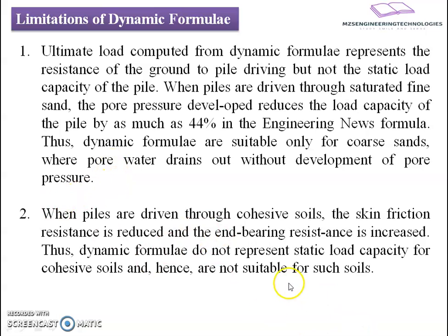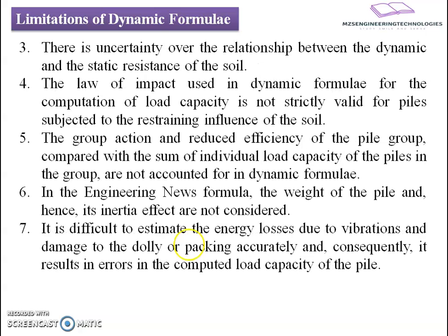When piles are driven through cohesive soils, the skin friction resistance is reduced and the end bearing resistance is increased. Thus, the dynamic formulae do not represent static load capacity for cohesive soils and hence are not suitable for such soils. So this type of formulation is not suitable for cohesive soils. There is uncertainty over the relationship between the dynamic and the static resistance of the soil. So there is a lot of ambiguity, or there is no direct relationship between the dynamic character and the static characteristics or resistance of the soil.